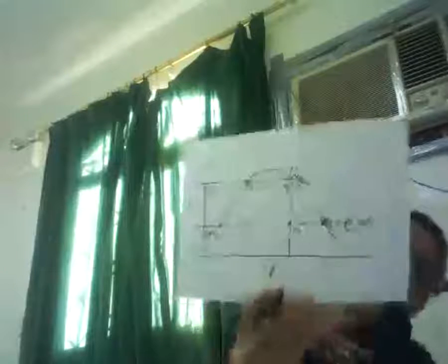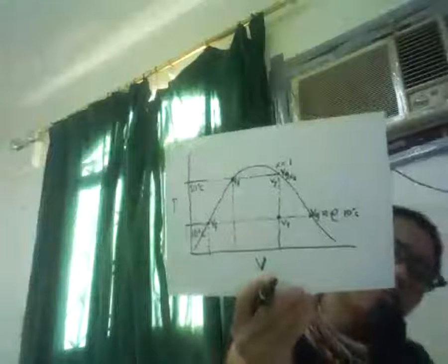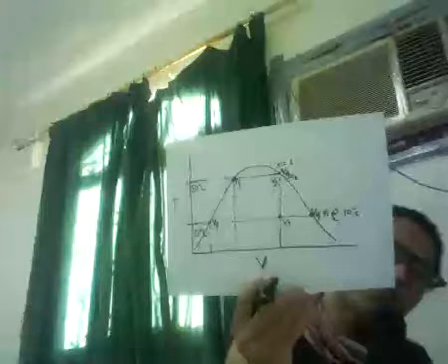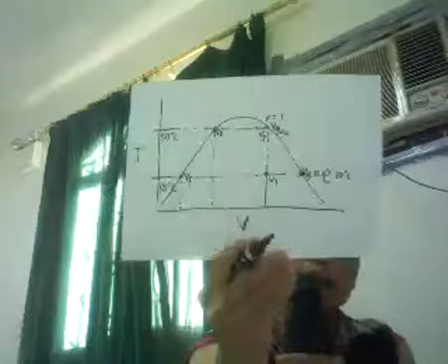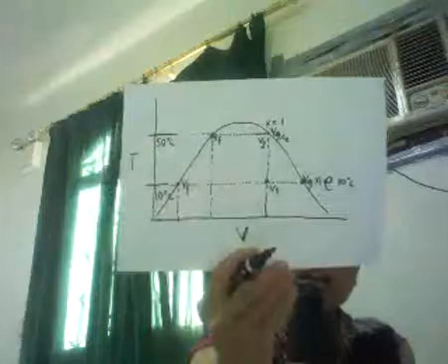Okay, so in here we have the x1 and the x2 also. Dryness fraction in 2, so like this. Okay, and x1 also somewhere here. X1 dryness fraction, x2 dryness fraction at 50 degrees. Yes, mass fraction. Or if you want it to be volume fraction also, it depends on what you want to solve. But here we are solving for the mass of the vapor present.